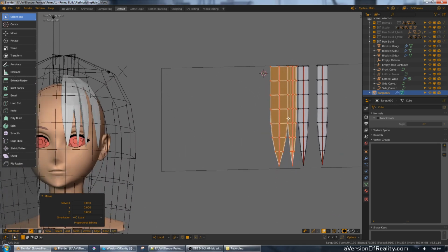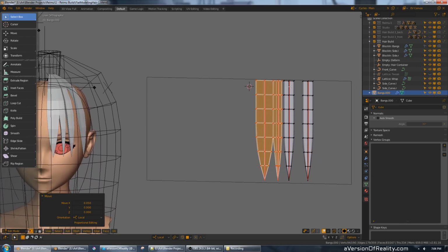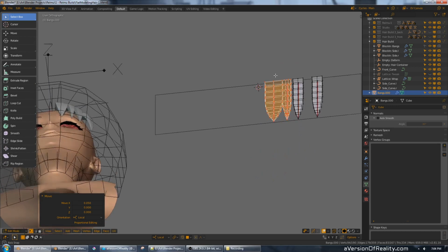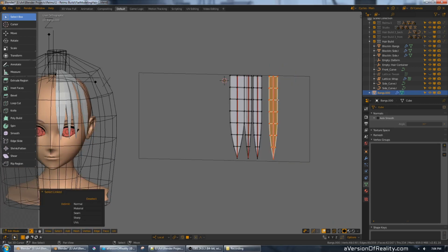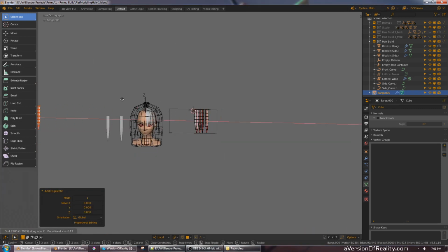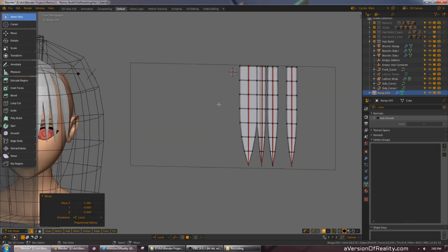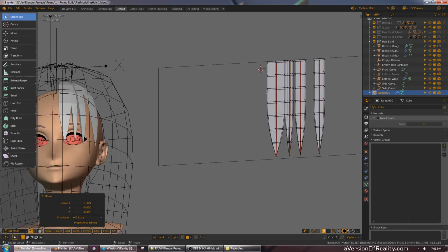But we can make this a bit more interesting still. Let's get some more depth and shape to this. First, before I go further, I'm going to grab one of my generic spikes, duplicate it, and move it way to the left on X, out of the way, just as a backup, so that if I use all of these, I can copy that and move it back.